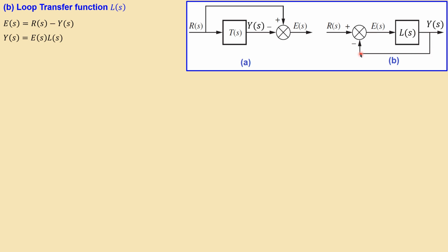This must be unity. That is mandatory to be able to calculate this in this configuration. We will do that later for non-unity-gain feedback configurations and then work out those situations also. If I now combine these two, so the error and also the output, you will have now an expression for error in terms of the reference signal and also the loop transfer function L(s), which recognizes that the 1 plus the loop gain is in the denominator, and also we have the input in the numerator.